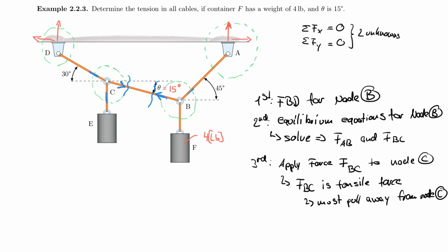And therefore, you actually have this middle part also in tension. And that really allows you to keep equilibrium throughout, and also makes sure that you have tension from here to here, from here to here, and from here to here. So please understand that you need to apply the force sometimes opposite depending on what force state you are dealing with here. But yeah, so my point to you is pull away from node C.